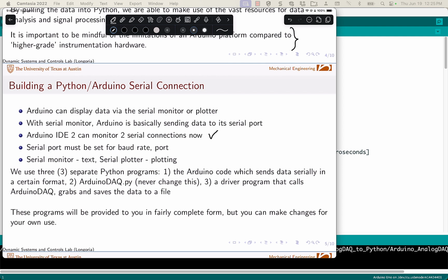So it used to be that if we were running this with PySerial, we couldn't do that. I think you can do that now. And then also you have to be mindful of baud rates and what port you're using, right? You need to tell the software on each side what the baud rate is and which port it's communicating through. Again, all of these things you'll quickly review in this first lab, and then we'll use them in subsequent labs. You get a better understanding of it.